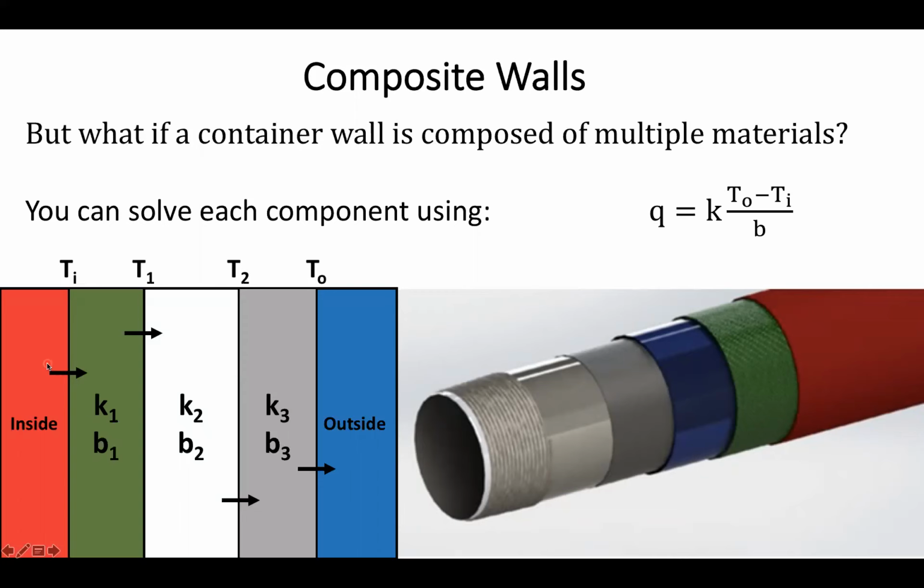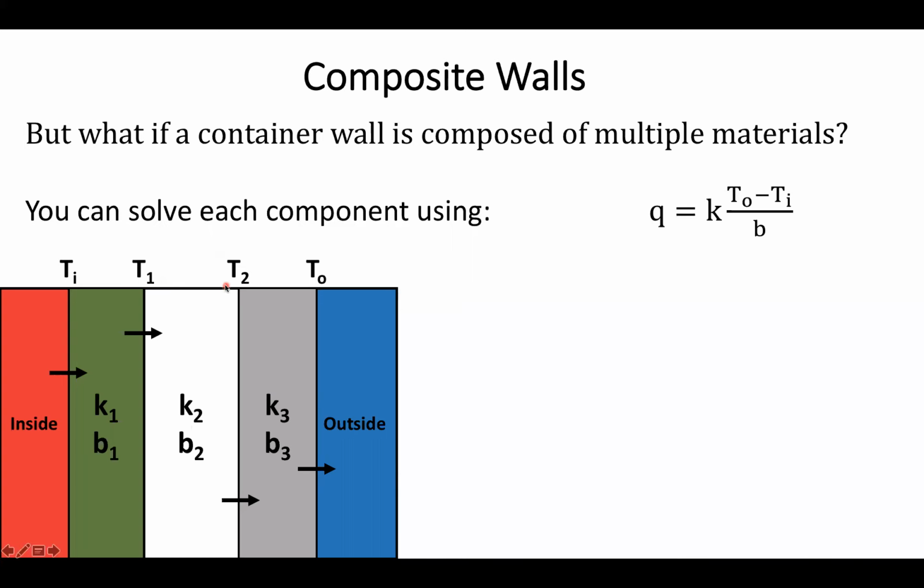If I know the inside temperature and the temperature at the interface in between the walls, I can simply use Fourier's law to determine the heat flux going through the material. And then based on the steady state principle, we can assume that we'd have a similar heat flow going through the other two. But let's be honest, this gets a little bit messy as I'd have to figure out what the temperature is at the interface. So I might need a simpler method.